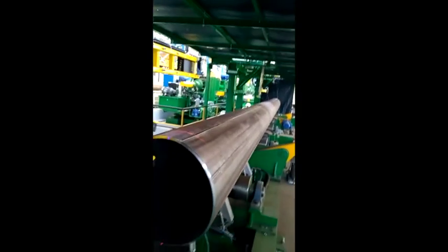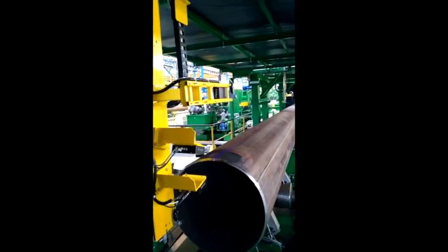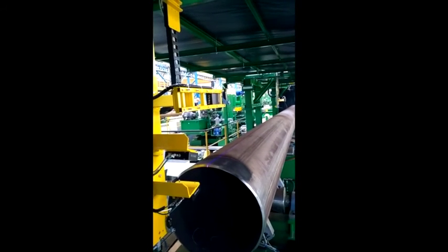After positioning the pipe and the sensors in the inspection position, the pipe is rotated and the sensors scan the pipe along the whole perimeter. In this way we measure the following parameters: bevel angle and bevel dulling of the pipe, wall thickness, diameter, roundness and cutting angle of the pipe end.